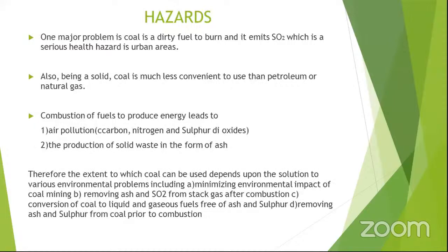The hazard of coal as a fuel is that it is a dirty fuel. It's termed a dirty fuel because it is not very friendly to operate; once you are exposed to coal, you are exposed to ash and all. It also emits SO2 in a very large amount, especially bituminous coal and lignite.